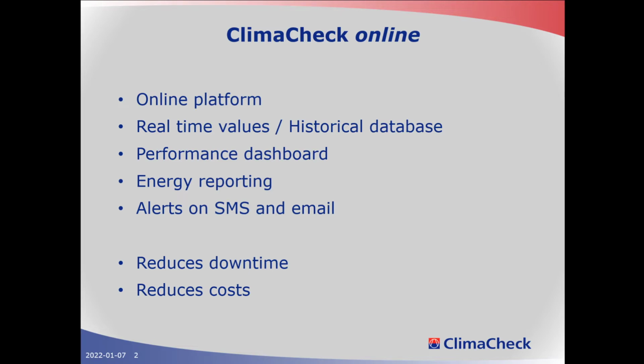Basically, it's a platform where you send real-time data. Your measurement is done on your machine, on your chiller, or on your system. The data is sent to our online server, and all the data is stored there, and all the calculation and presentation is done online through a web browser. This is to compare with the PC software, where you're just making the logging or the measurement locally with your system and logging in with your PC software. Now you're measuring with the same hardware, but you then send the data to our online server.